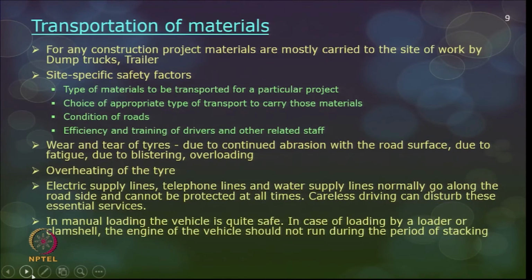Transportation of materials. During transportation also there are a lot of precautions you have to follow. Transportation on a site most often happens with the help of dump trucks or trailers. Site-specific safety factors: you should always think of the type of material to be transported, the choice of appropriate transport, the condition of the road, and the efficiency and training of drivers. These will decide the load limit, the type of material and the choice of equipment for transporting materials. You should also note wear and tear of tires.